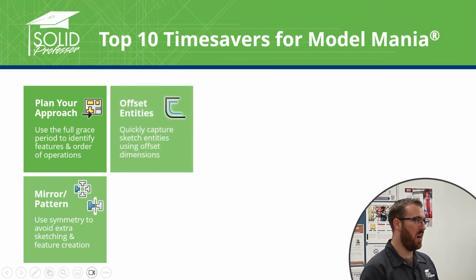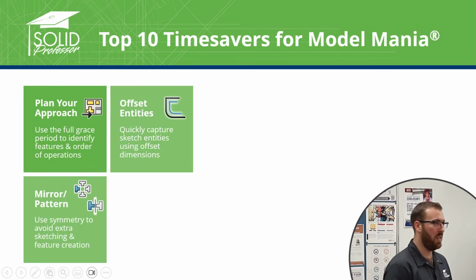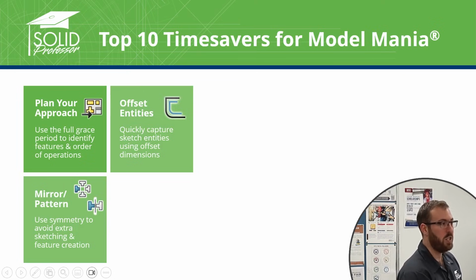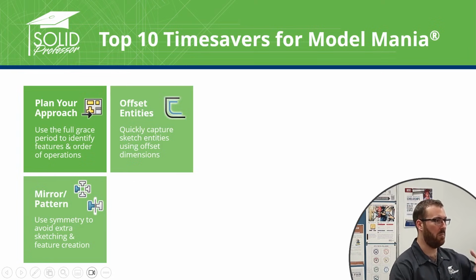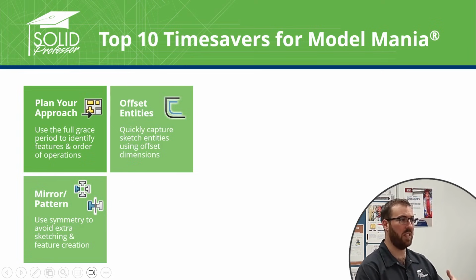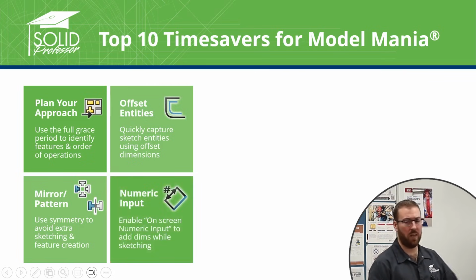Offset entities is common in every Model Mania exercise that I've done. They're super common in certifications. Figure out which dimensions on your sheet are offset dimensions. It's usually fairly easy to tell because the leaders will be attached to some other obvious part of the model instead of self-contained. Those can be offset dimensions and you can create those very, very quickly.